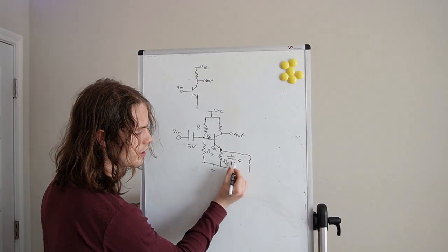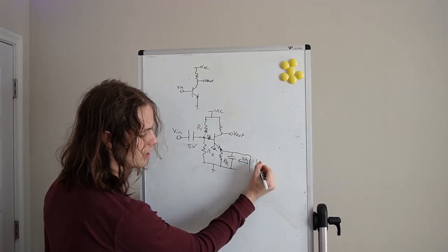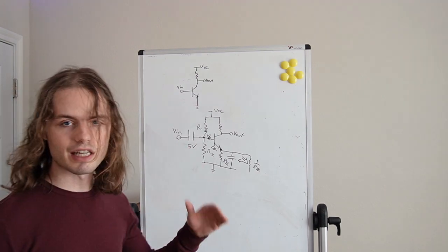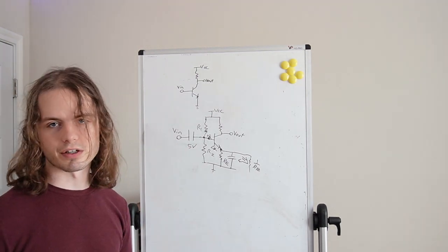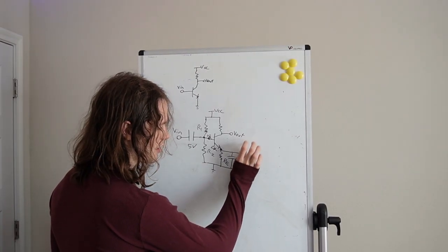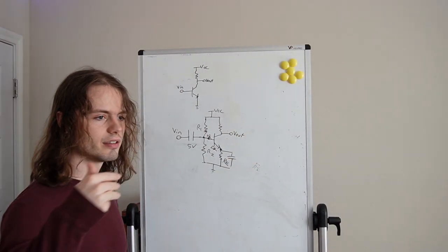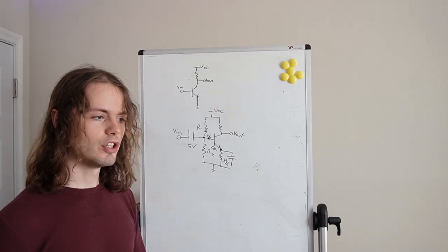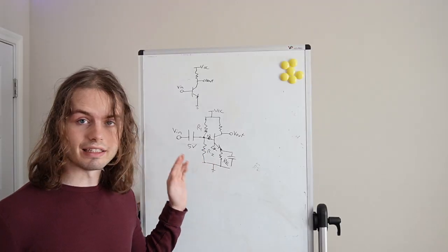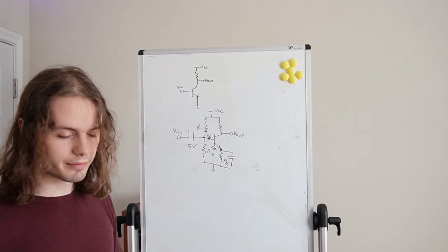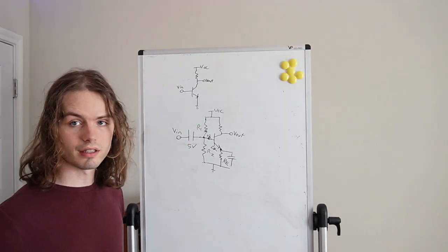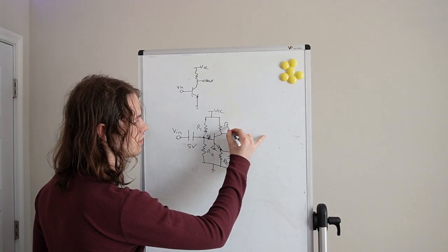So you could, in theory, choose this capacitor's impedance to be 1/10 of RE, which means that there's less negative feedback, meaning it gets amplified better. So that's what that capacitor is for. It's the bypass capacitor to allow your AC signal to still get amplified while still getting that DC benefit of negative feedback. Okay, and lastly, the component we saw in both examples, this is the collector resistor, RC.